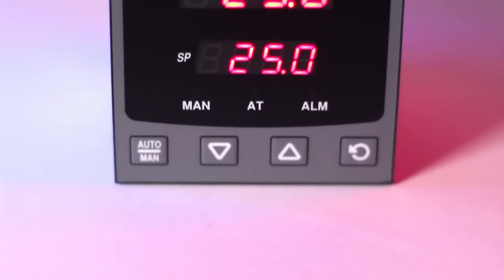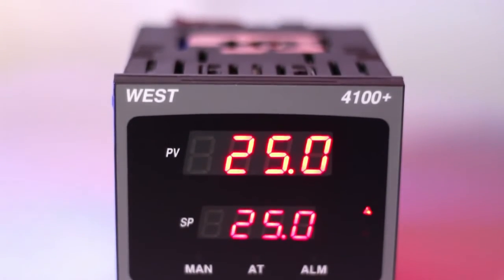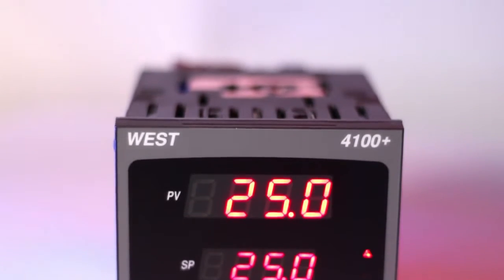In general, if stable control is required and other factors don't prevent it, I would always use proportional control. In fact, there are some applications where on-off control cannot be used. For example, if your controller had an analog output, such as 0 to 20 mA, perhaps for a modulating valve, proportional control has to be used.